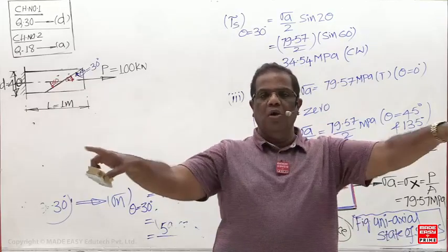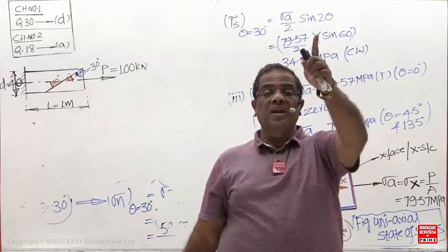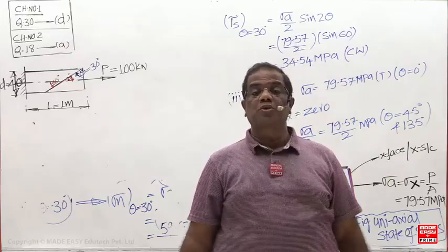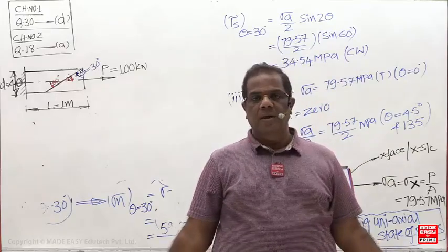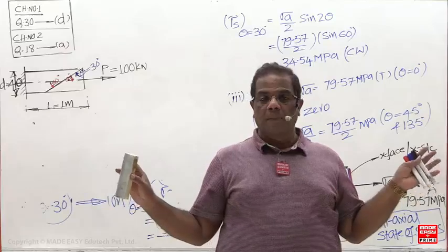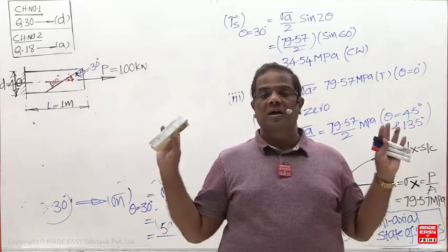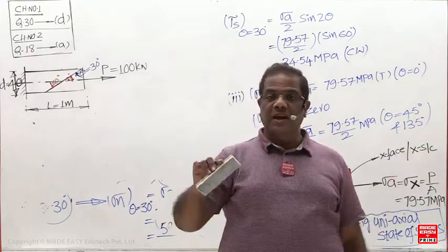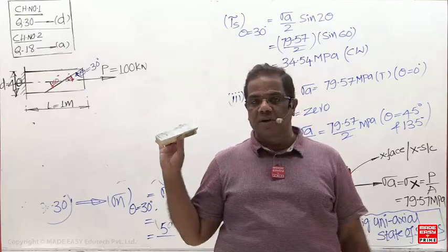In pure axial loading, stress is developed only on one perpendicular plane, and the remaining two perpendicular planes have 0. The state of stress will not give the stress on an oblique plane, it gives only the stress on three planes. On the three planes shear stress is 0, but on an oblique plane it will not be 0.